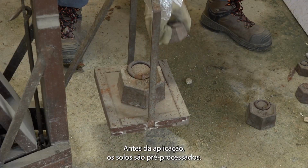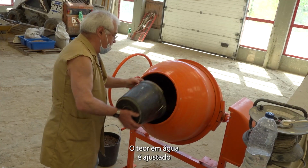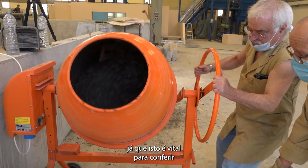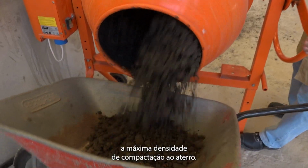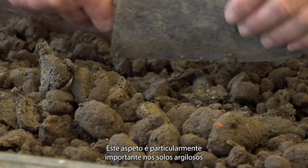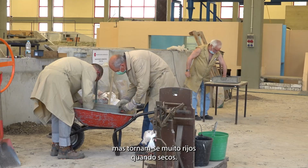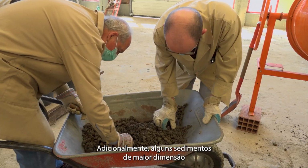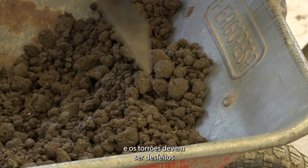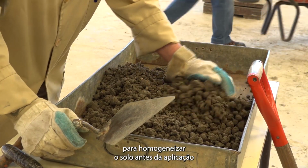The soils must be pre-processed before application. The water content has to be adjusted to the optimal value from the Proctor standard test, since this is vital in order to obtain the highest density from compaction. In clay soils, this is particularly important because they are moulded when wet but become very hard when dry. In addition, some pieces of rock of very high dimensions have to be removed from the sample and clods must be crushed to maximize the soil homogeneity before application.